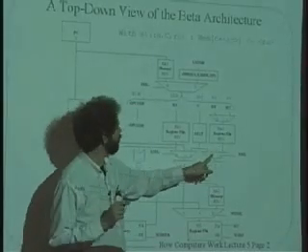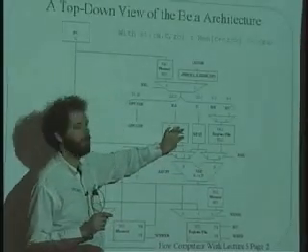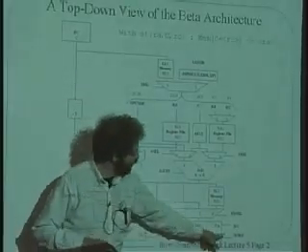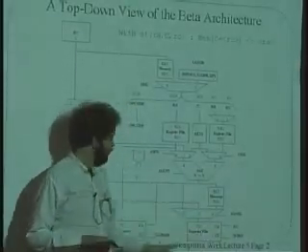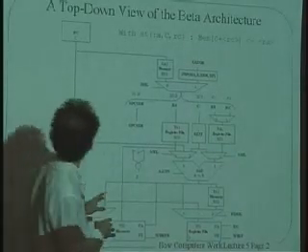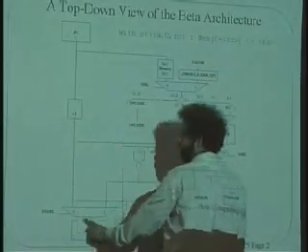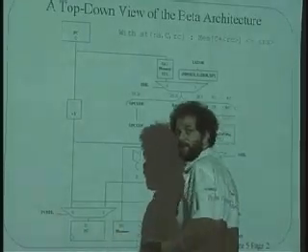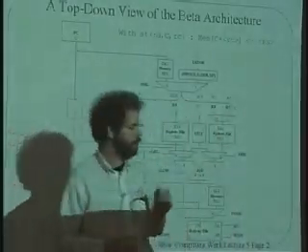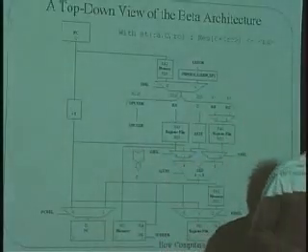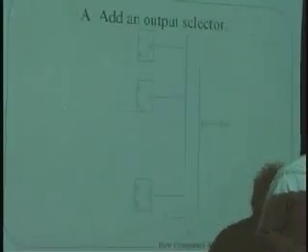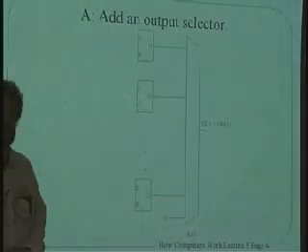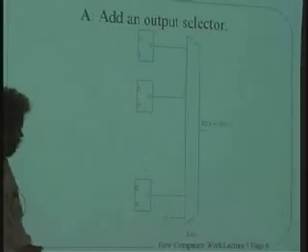And so the first question that comes to mind is, if I'm going to build this thing out of 32 units which look kind of like the program counter here, where there's just a 32-bit number held in one thing, how do I choose which of the 32 gets read by any one of those read ports? And the answer is actually very simple, and you've already seen the part which allows you to do this.